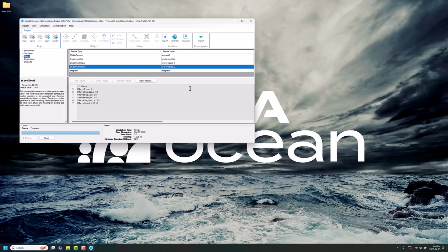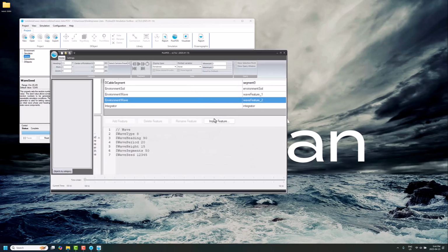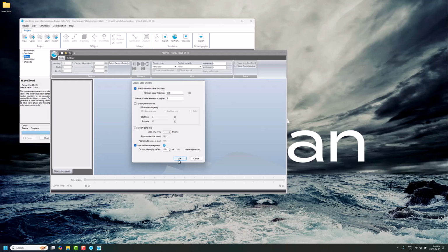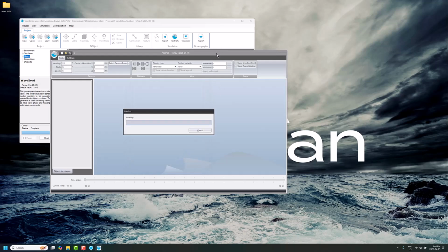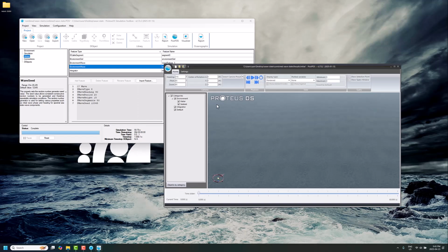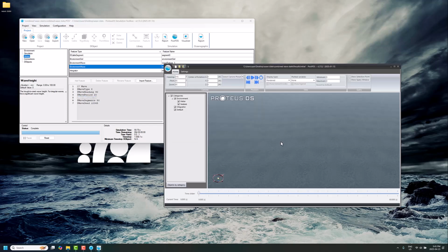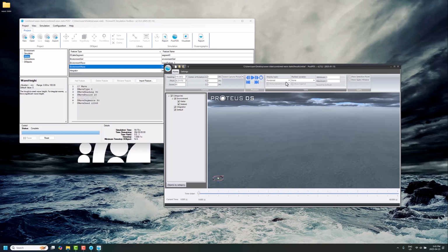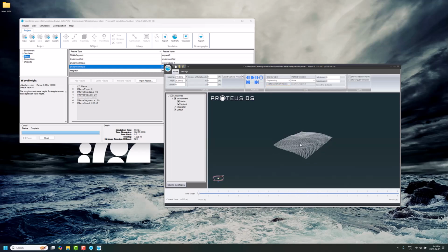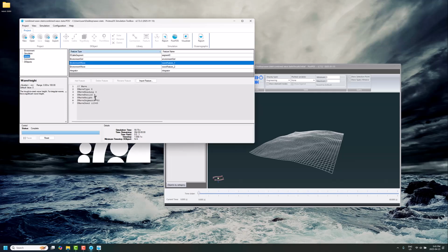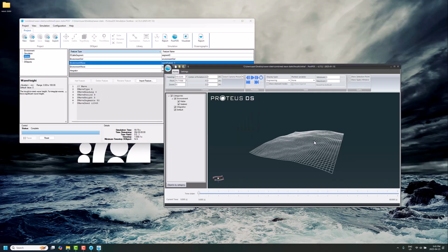Now, one thing I wanted to highlight when you do this is you lose a little bit of the meaning of the input states from what's actually being simulated. When you're specifying the significant wave height of the input spectrum, that's one thing, but now we're really superimposing these two spectrums on top of each other. So the as-simulated sea state is not going to be some obvious combination of that 15 meter sea state and the other one that we did, 5 meter significant wave height. So you've got to be a little bit careful about the meaning of doing that.